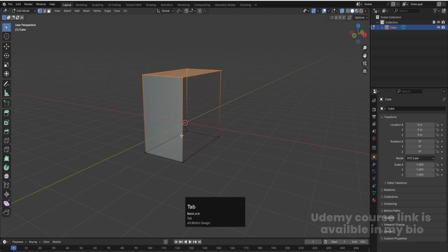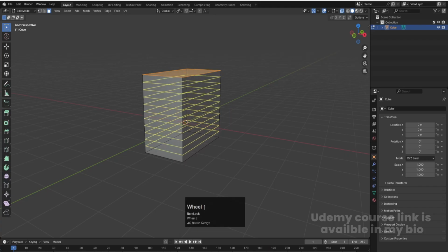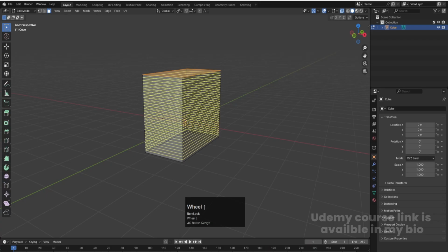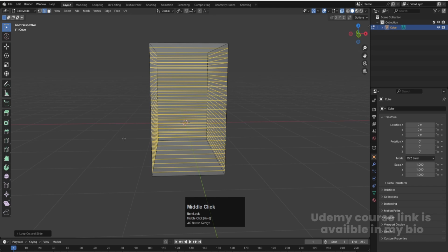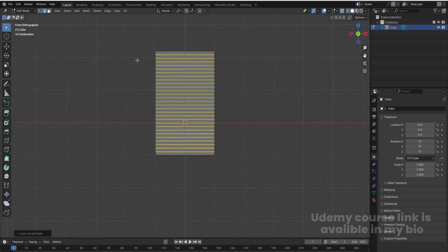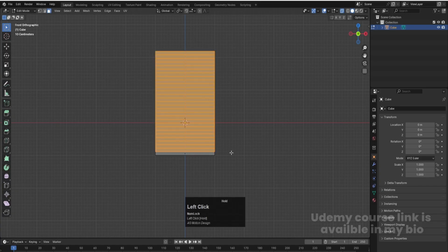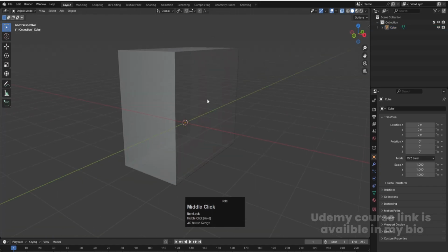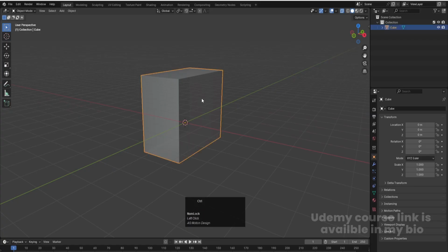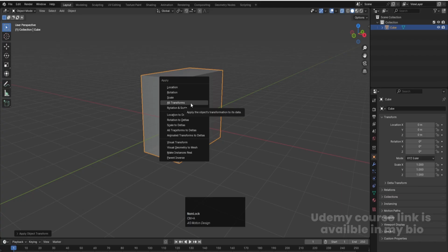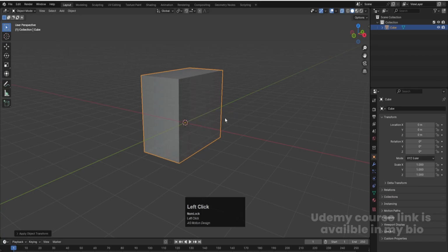Now go to the tab view and press 3 for face selection, and hit Ctrl R to apply loop cuts, and simply scrolling we can create multiple cuts like this. Okay, and simply click over here like this. Now let's go to the front view over here and press 3, which is a shortcut key for face selection, and we are going to select this much faces. But before that, make sure that you go to the edit mode by hitting tab, select this and hit Ctrl A, and make sure to apply scale. Hit Ctrl A, choose apply all transform and apply rotation scale as well.